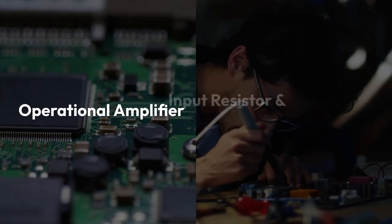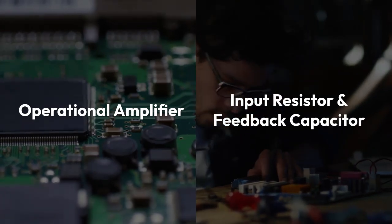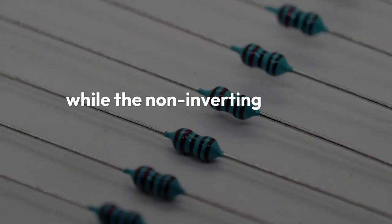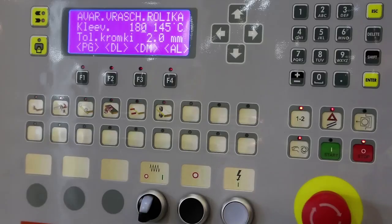At its heart, an integrator circuit uses an operational amplifier, an input resistor, and a feedback capacitor. The input signal is applied through the resistor to the inverting input of the op-amp, while the non-inverting input is typically grounded. The capacitor is connected between the op-amp's output and its inverting input.